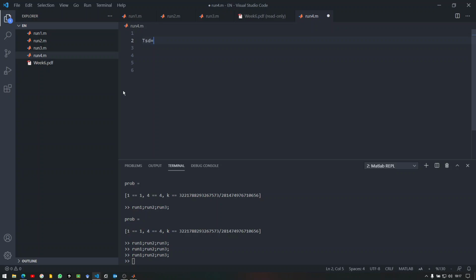We know what the characteristic polynomial should look like if we are using dominant pole placement, so we might also construct, using this constructed closed loop transfer function, a candidate one that is based on this polynomial. And using that and not restricting the structure of the controller, but doing kind of a reverse engineering here, we would also be able to propose a controller.